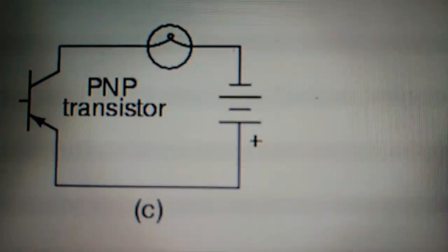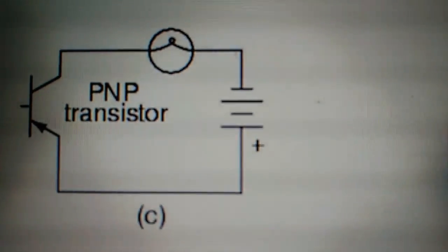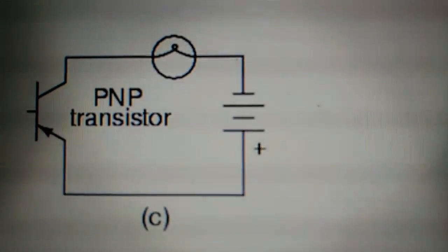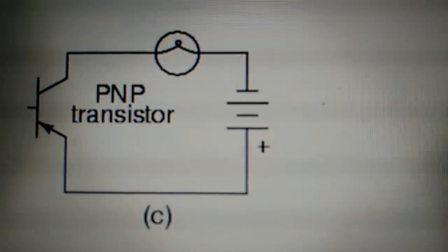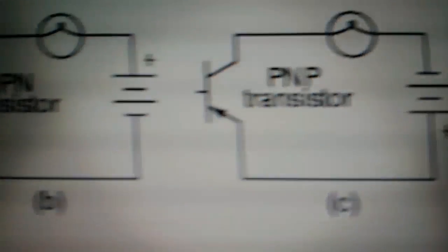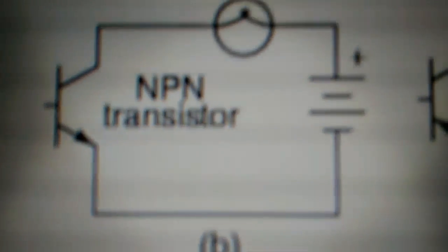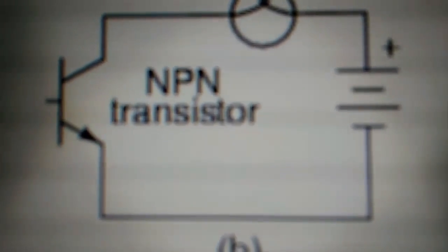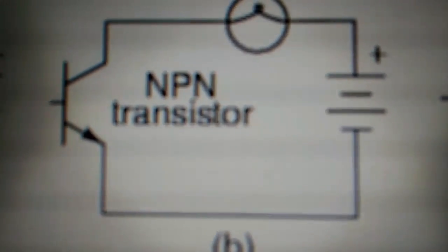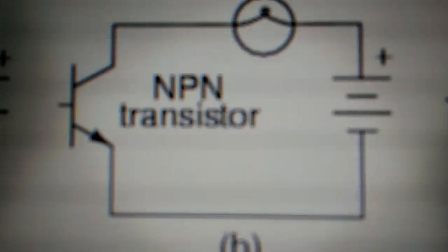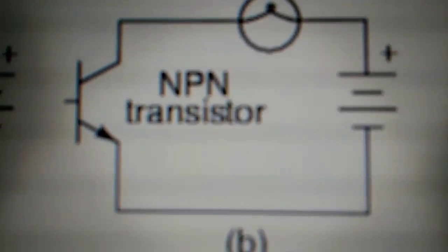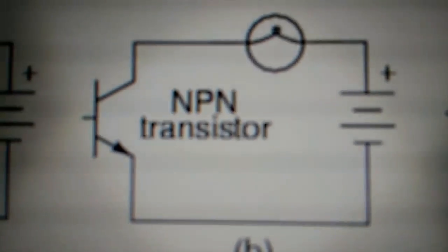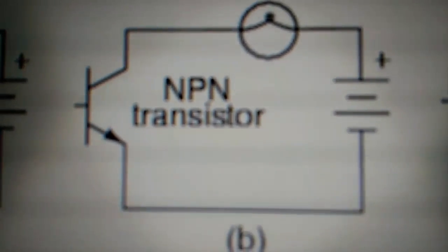Going back to the NPN transistor in our example circuit, we are faced with the need to add something more so that we can have base current. Without a connection to the base wire of the transistor, base current will be zero and the transistor cannot turn on, resulting in a lamp that is always off. Remember that for an NPN transistor, base current must consist of electrons flowing from emitter to base against the emitter arrow symbol, just like the lamp current.